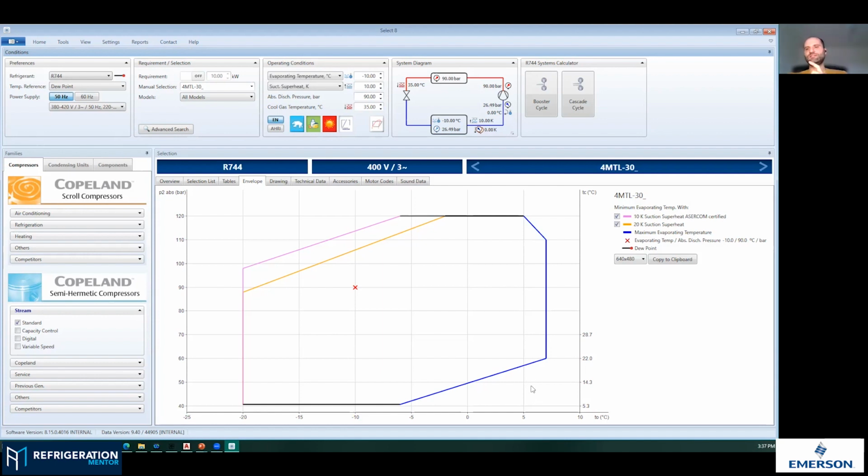If you don't have it, it can start fluctuating up and down during one discharge cycle, because the force of the spring of the reed is pushing down, but you are pushing from the bottom with the pressure of the gas. If this is not well balanced, and you start pushing it up and the discharge reed opens, it can happen that it doesn't stay open during the full cycle and it starts flappering. It may lead to the breaking of the valve plate. So this is one of the important things.